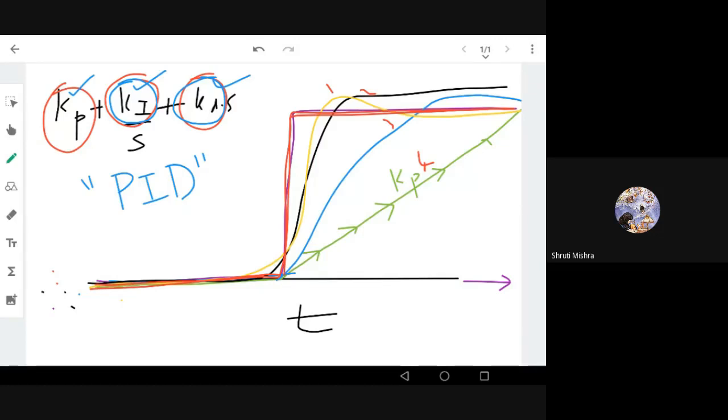So that is called tuning. This process is called tuning. Finding optimal values for these constants is called tuning. What is tuning? Tuning of a PID controller, or tuning of a controller, is selecting the optimum values for the proportional, integral, and derivative controller, so that my plant output immediately follows, or follows with less error or with great stability, my reference input, right? So how to tune and what are the factors? It depends on the application. What kind of application are you working on?